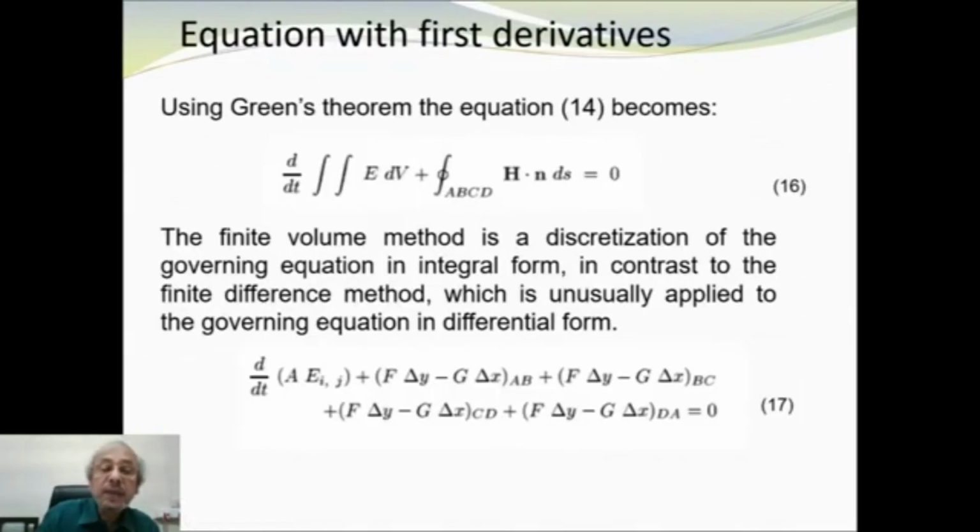Now, basically, when we are integrating, we are integrating mass flux, because F is nothing but rho into u into delta y. That means delta y into unit depth is the area through which rho into u is passing. That means u into area gives the volume, and multiplied by rho gives the mass. So through the control volume we basically calculate the total mass flux in x direction, the total mass flux in y direction, and then this net mass flux will be 0.